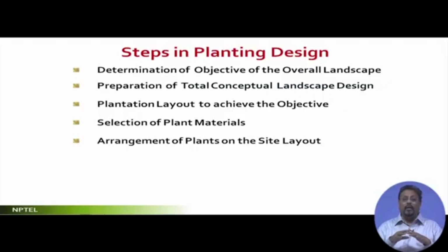See, originally when you made the layout, basically what you did is you very roughly placed it and tried to understand, okay, this is the area where I need the shade. Let's take an example of an avenue, which I'll be discussing in much detail in the second part of the lecture series, but at this moment I'm just citing an example. I have this particular road which is to be shaded because it's in a hot arid zone, and shading of the roads reduces the incident radiation first of all, and then the reflected radiation by virtue of the thermal heat that it is storing by itself and then radiating upwards, if you want to reduce it. So objective-wise you are just saying, okay, this particular road will have a series of trees on either side, fine, no problem.